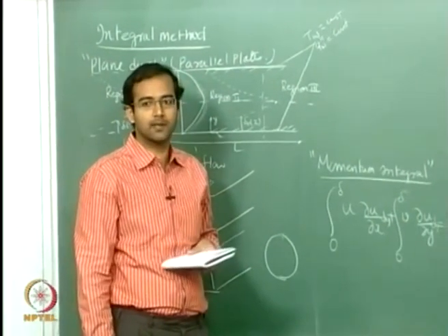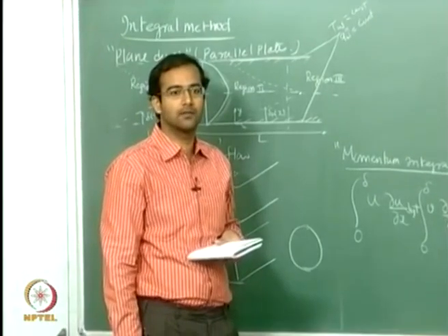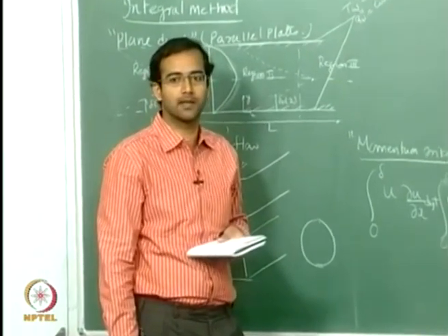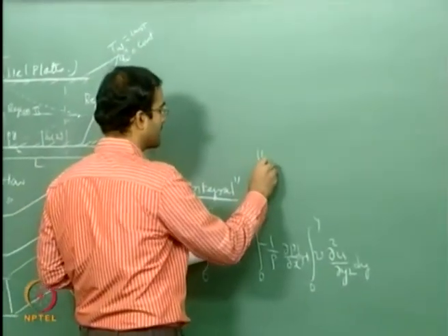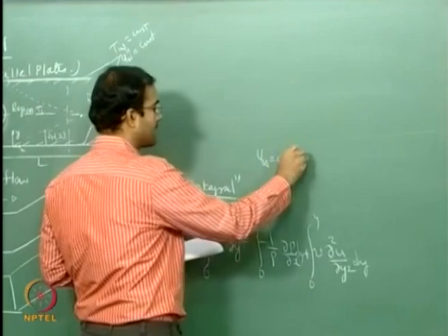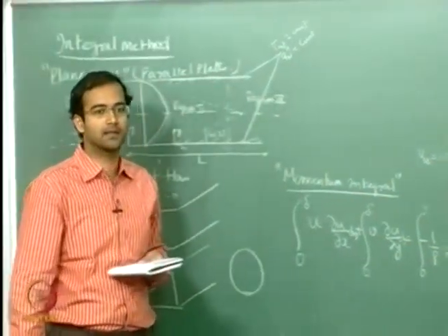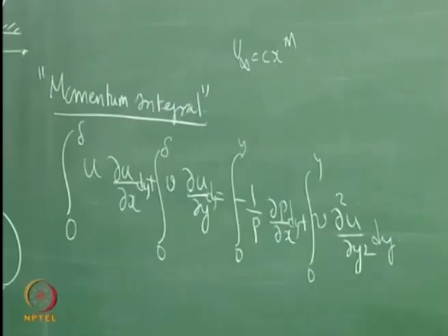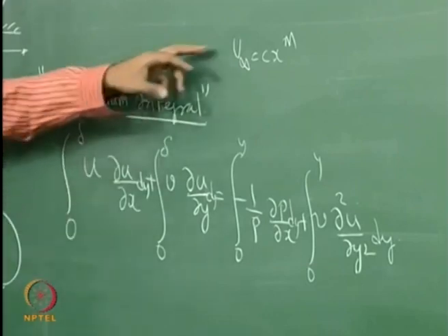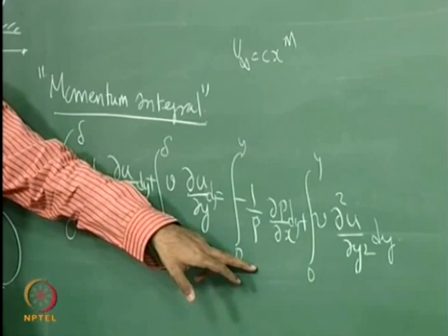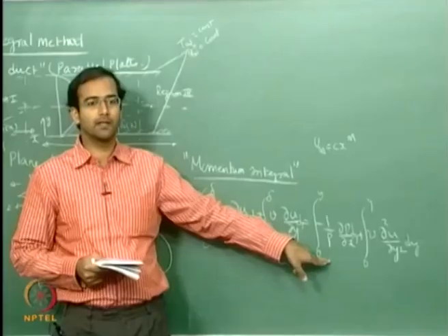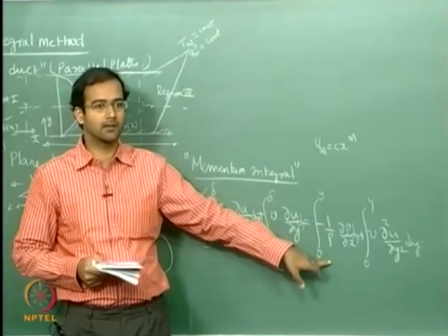So when you have a pressure gradient term, you should know how the free stream velocity is varying. For example, in the external flow case, you took free stream velocities which are varying of this form. This is the Falkner's kind of a profile. So you should know what is the variation, and then you can substitute for dp by dx as du infinity by dx. However, in the internal flow case, it is not very clear about this.